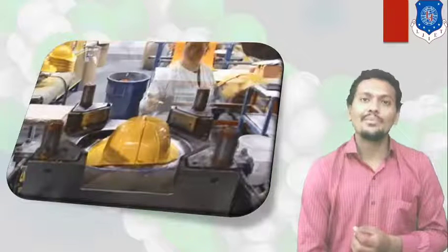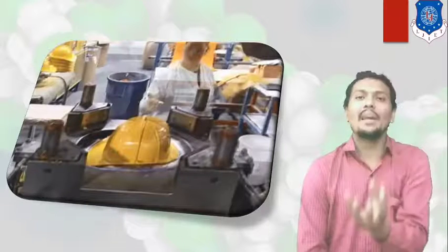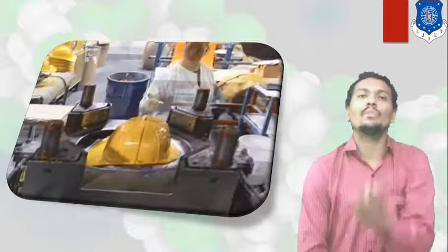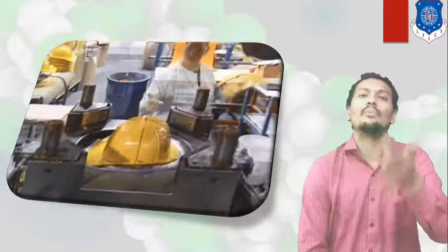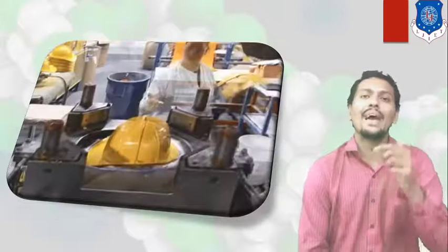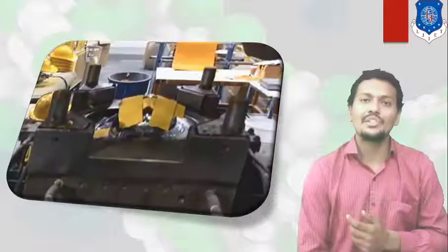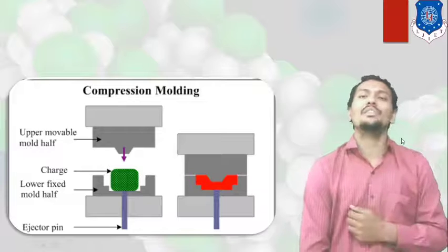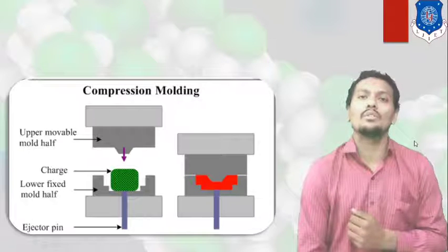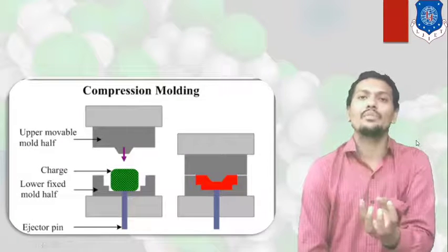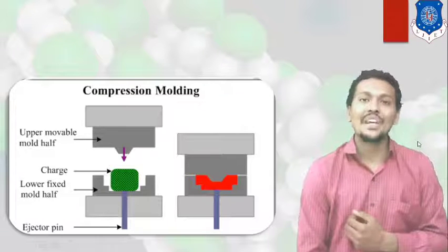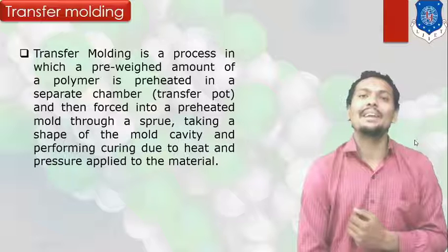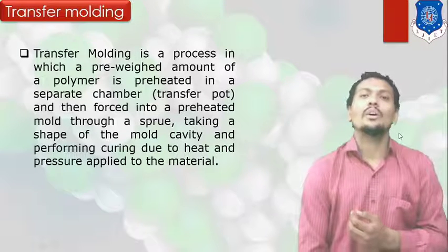In the compression molding, you can apply your upper part of piston, and with the help of compressive force your final plastic can be molded according to your die shape, right? Here I mentioned the image for the compression molding also. With the help of compressive force you can reshape your component, and after that you can easily eject your component.